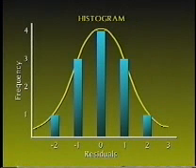At this time, it's usually a good idea to create a histogram from the information we have calculated so far. A histogram gives us a graphical representation of the precision of our work. In the histogram, we plot the value of the residual, shown along the bottom line, versus the frequency of each value, here shown along the left side. The -2 residual occurs one time, the -1 value 3 times, and so on. When you connect the location of each value with a smooth curve, the result is the standard probability curve.